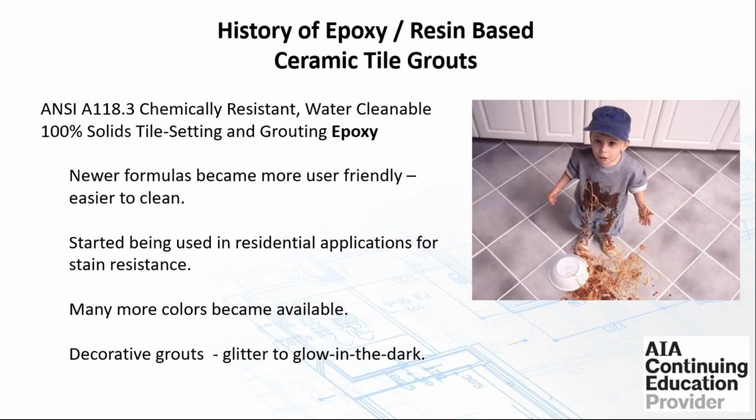When you take a look at where we're going with epoxy grouts, we're seeing it more and more often used in residential and other applications where you want color consistency and you don't want to go into staining of the grout or ease of cleaning. The Coca-Cola spilling on it, the red wine, the spaghetti sauce: this will clean up off the grout and you'll end up with a consistent color. The newer formulas are a lot friendlier and easier to clean, a lot easier to work with and clean up during the application.